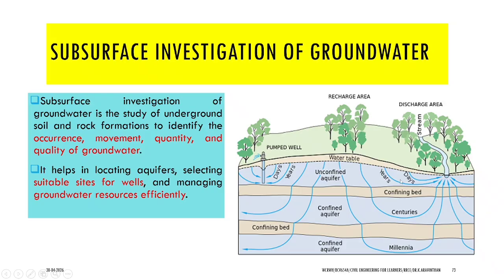If you go far away from that, you can understand that this water will immediately get penetrated inside in days. If you put a bore here, you will get a continuous supply of water. Why? Because you have a river source, a surface water source, so this water gets penetrated. What happens if you put a bore wherever the ground level is very high and there is no source of surface water and water percolation?